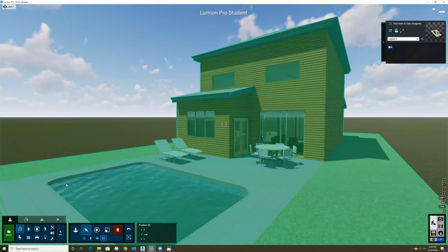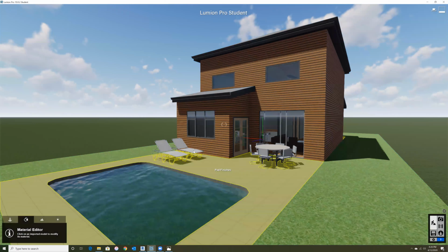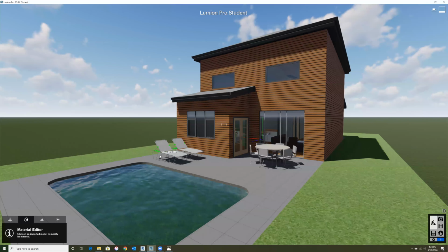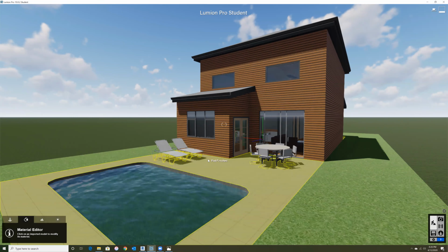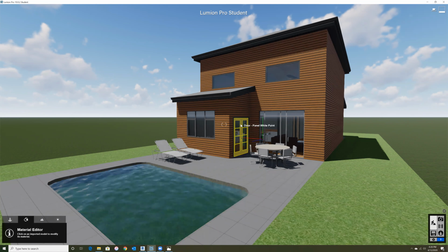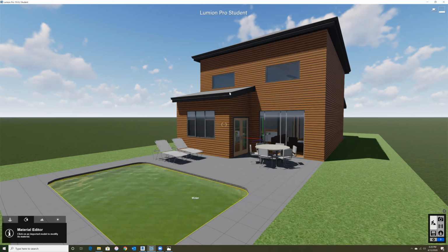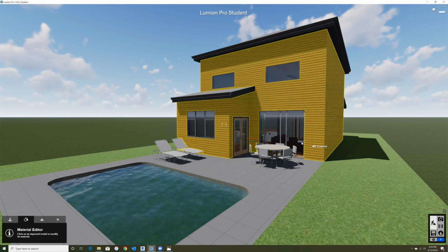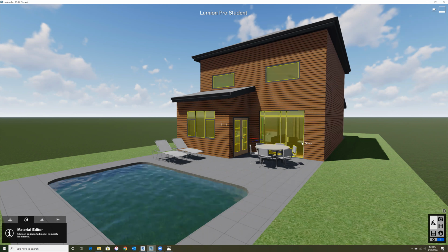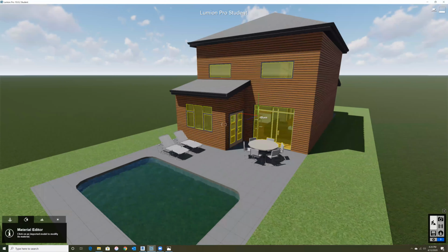So with our building here, in order to change materials, we can go to the Materials tab here on the bottom left-hand side. The Materials tab will let you hover over any material in Revit that you have defined as something different. As I build up my Revit model, I'm constantly replacing those assets for the materials. What that allows me to do is change everything independently once I get to a program like Lumion. You'll notice as I'm touching the top of this table, or even the water itself, these materials act independently of one another. If I would have used the default material that Revit gives all walls and all floors, they would all change together and I would not be able to use a variety of different materials. So you notice with the house, I've already changed a few things.